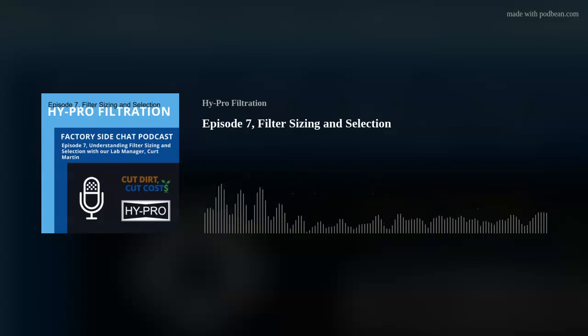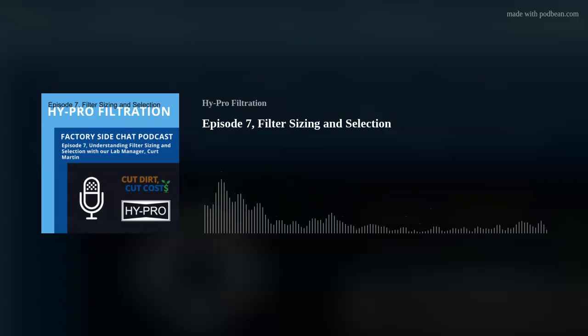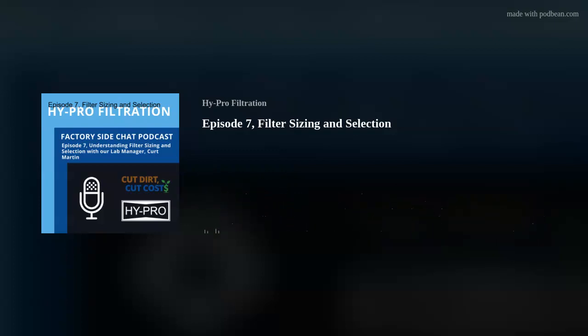For really high ISO codes, we will sometimes offer larger dirt holding capacity elements versus smaller elements to reduce the downtime for changing elements. So those are some of the things we look for when sizing carts, skids, panels, that type of stuff.